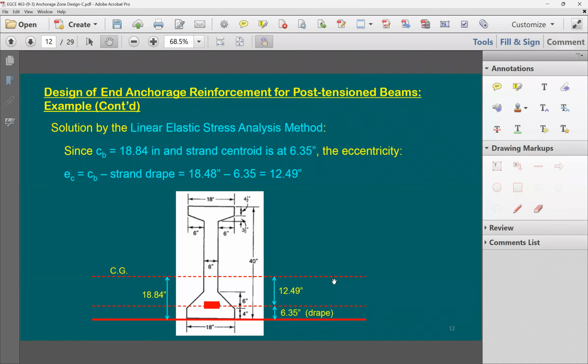Now, this shows you, when you have plenty of strands and you'd like to distribute them, but you're not planning to make them uniform. For example, when we did the double T, we decided to go with 4 strands in each leg or web, right? We said that we're going to have 8 strands, correct? Anyone recall the 8 strands in the double T?